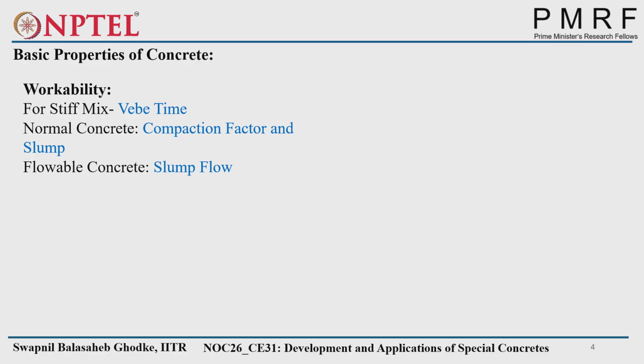So first of all, we'll see the basic fresh properties of the concrete. Concrete should be workable. Why should it be workable, and why should it have a sufficient initial setting time? Because if we cast the concrete, suppose we are casting a beam or column, we should have sufficient time to pour into that cast specimen, and we'll get the proper compaction also.